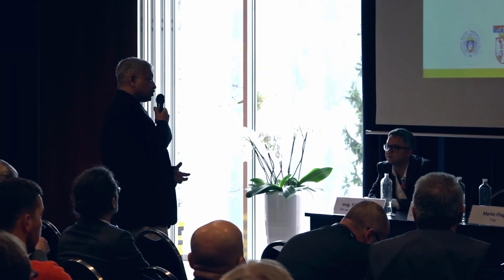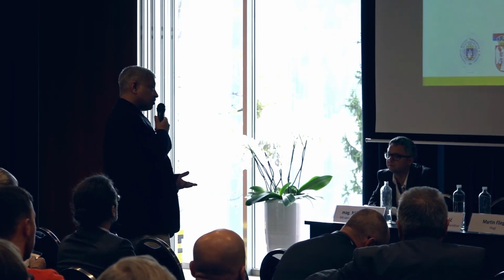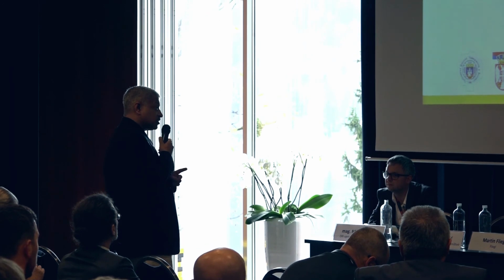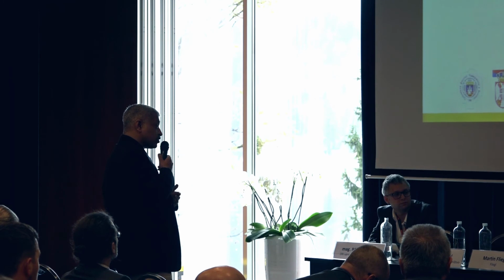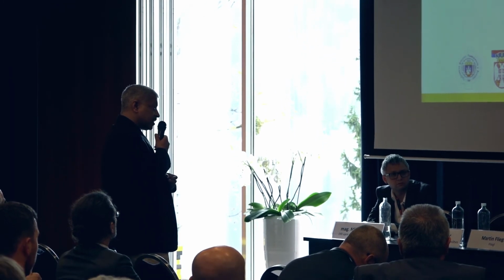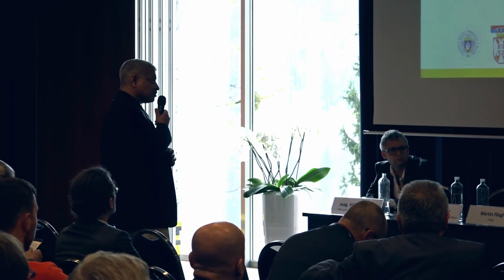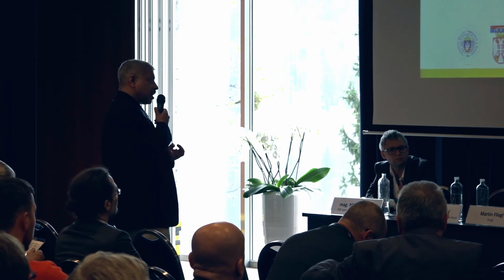Excellent presentation. Does the hydrated lime which you use work on all aggregates? Does it work on granites and gabbro as well? Or is there a consideration in terms of the type of aggregate? That's one. And the second one is, have you also looked at the ASTM boil test, which is more like a torture test because it tests the mixes at 100 degrees Celsius?